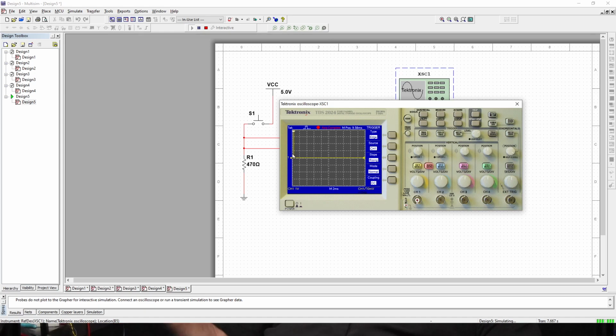Now this is a spike here. So you see, we can magnify it by changing this milliseconds per division. All right, so 10 milliseconds now, that gives us even smaller. All right, but we can do this, just keep going as far as we can. Oh, look at that, we can actually see it. And this is as far as we can go. All right, 2.5 nanoseconds is as much as we can go. All right, so we already see something.